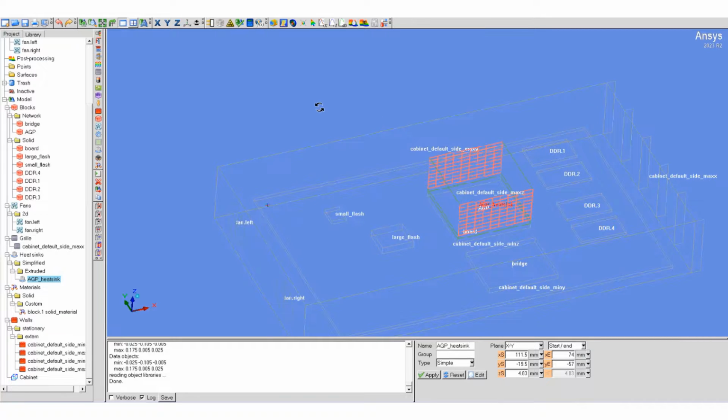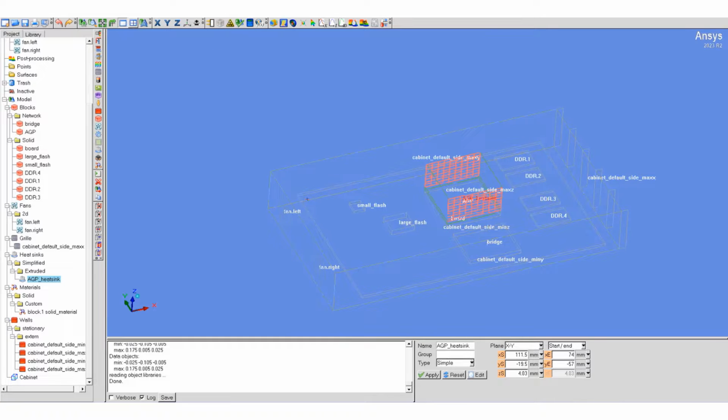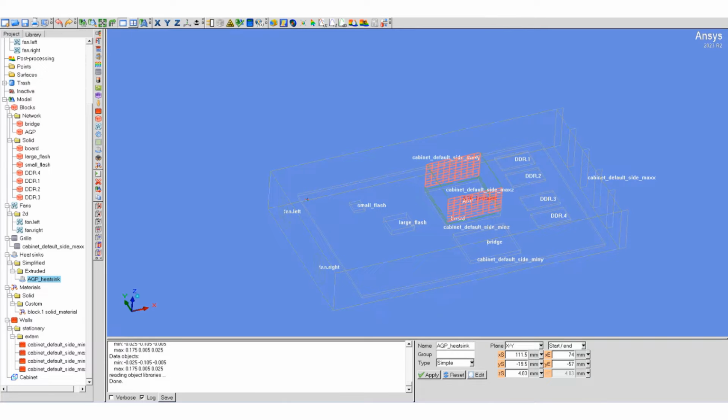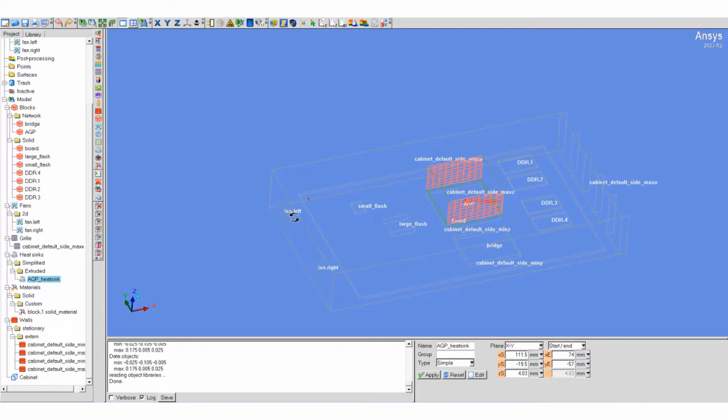In order to make sure all the objects are properly placed, we can use the distance. We can compute the distance between objects and debug the object placement. So what we will do is we will go to view, distance, and you can left click between two objects to view the distance.